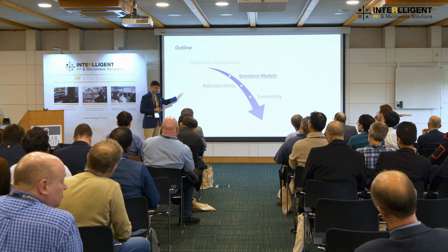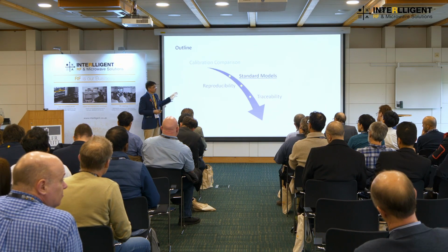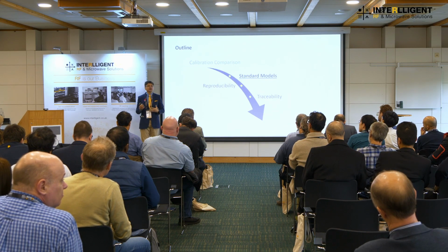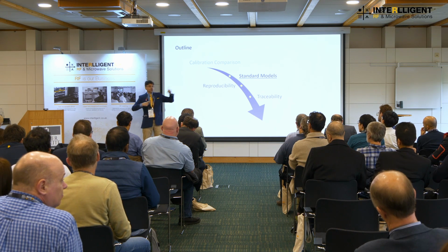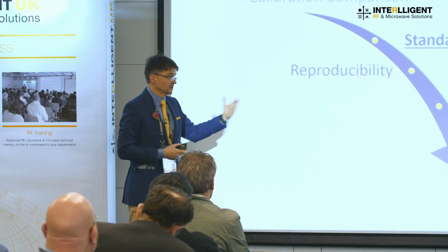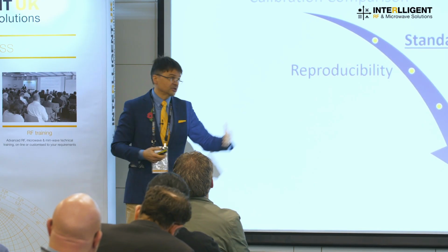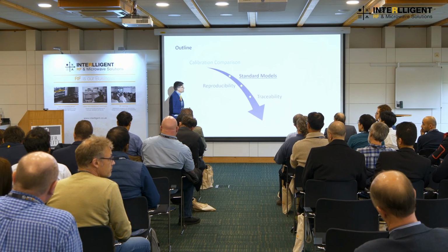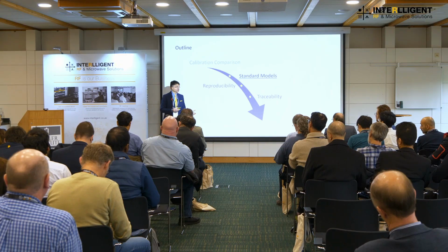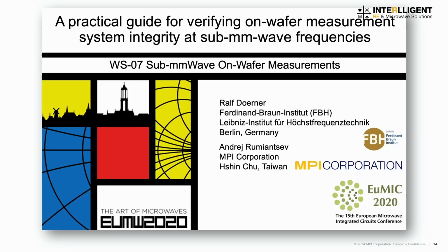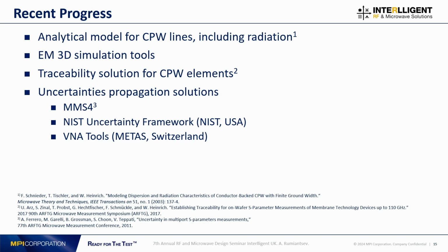But instead of using the reference material from NIST, you can rely on commercially available calibration substrates. If you want to link one setup to another setup, the same experiment can be done on commercially available calibration substrates, which can give you probe calibration up to much higher frequencies today. I don't have much time to guide you through another possible measurement approach, which we presented at European Microwave Week. You can find it on the slides. That was another kind of alternative. I have 10 minutes, but I have 2 more matters to explain.